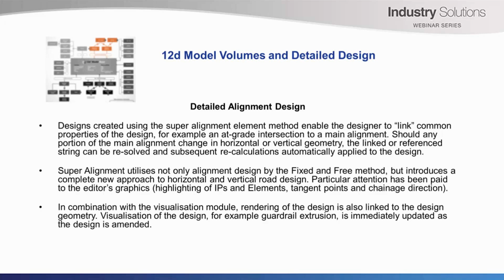Superalignment utilizes not only alignment designed by fixed and free method, but introduces a completely new approach to horizontal and vertical road design. Particular attention has been paid to the editor's graphics, highlighting of IPs and elements, tangent points, and chainage direction. The combination of the visualization module, rendering of the design, is also linked to the design geometry. Visualization of the design, for example, guardrail extrusion, is immediately updated as the design is amended.